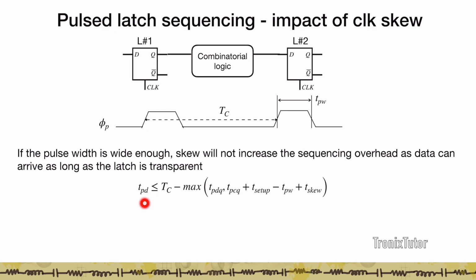And so therefore, if you think about the propagation delay because of skew, in the first case, it is limited only by TDQ, right? And it would be fine. The skew impacts only the other condition when you have the D arriving after the clock has come in.